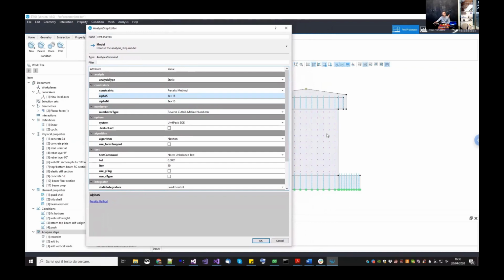Add a couple of numbers there, so it will be 6 because more elements converge to the same node, and then you have the thickness of the wall, which is 100. So it will be 7, and then you add 8 to that number. Why 8? Because 8 is half the number of significant digits for a double. So a double can represent up to 16 significant digits. Then you add 8.